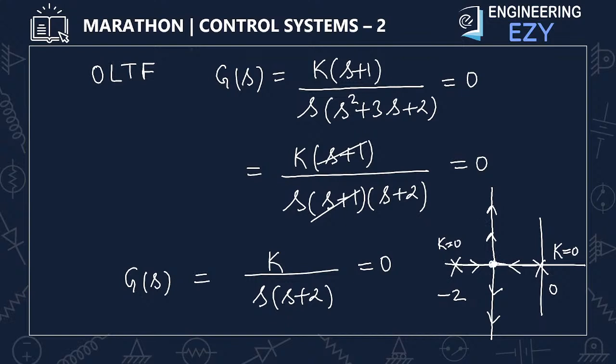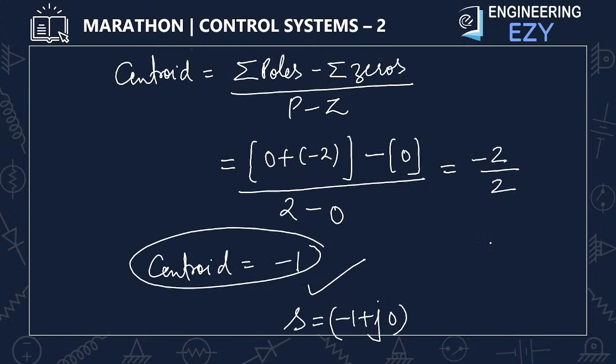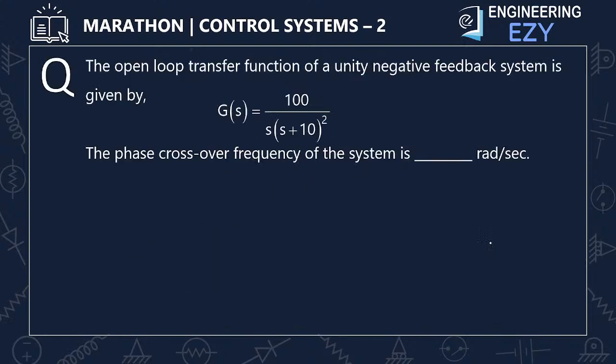So in this question, it is a special question. Centroid and breakaway point both are at minus 1, the centroid as well as the breakaway point. Centroid and breakaway point may differ, but in this question, they are the same.